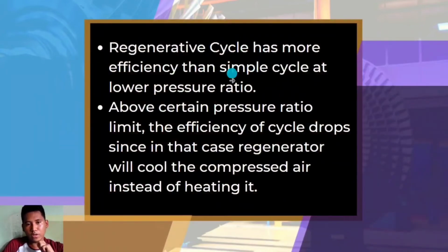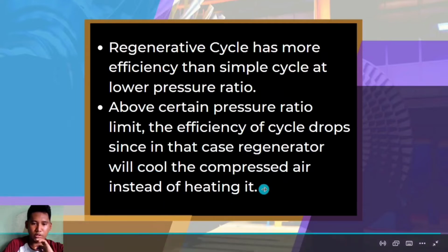Regenerative cycle has more efficiency than simple cycle at lower pressure ratio. Above a certain pressure ratio limit the efficiency of cycle drops, since in that case regenerator will cool the compressed air instead of heating it.